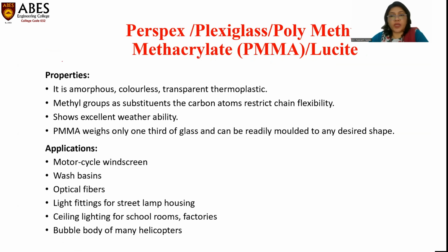Now the properties of polymethyl methacrylate are: it is an amorphous, colorless, transparent thermoplastic. Due to the presence of the methyl group as substituent, this polymer shows restricted flexibility. This polymer also shows excellent weatherability, it is weather resistant.